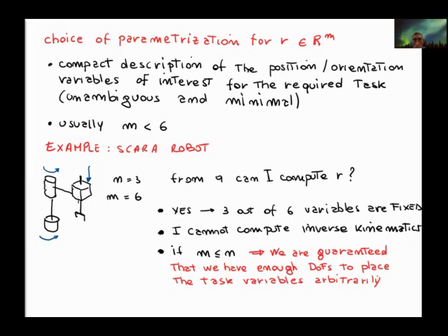Last lecture, we started to talk about the direct kinematics for a manipulator. And to start to talk about that, we were introducing homogeneous transforms. Some of you were asking me about the SCARA robot example that I was giving you. A SCARA robot, in this case, we are considering just the first 3 degrees of freedom. So think about a revolute shoulder and a revolute elbow and a prismatic joint. And 2 of the revolute joints have parallel axes.